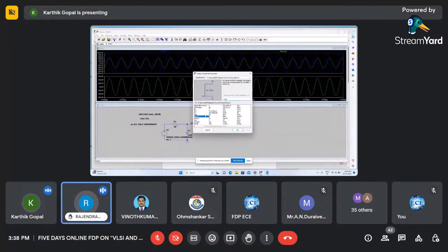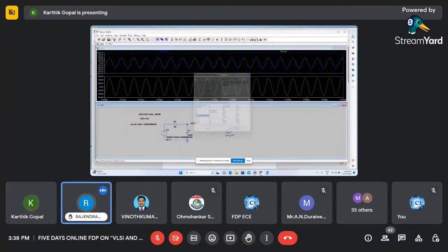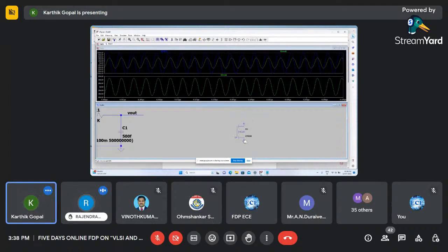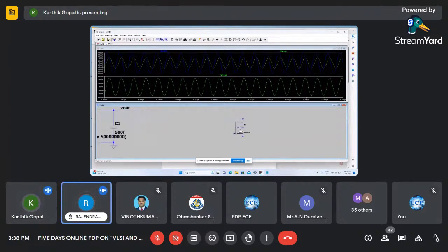CMOS N. So this CMOS N is the instance from the processor link. When you install LTspice, you don't have the CMOS N. So you need to follow those steps, and the models will be dumped in, and you copy and follow those steps. It will be done. It is very easy steps. So this is from the professor.